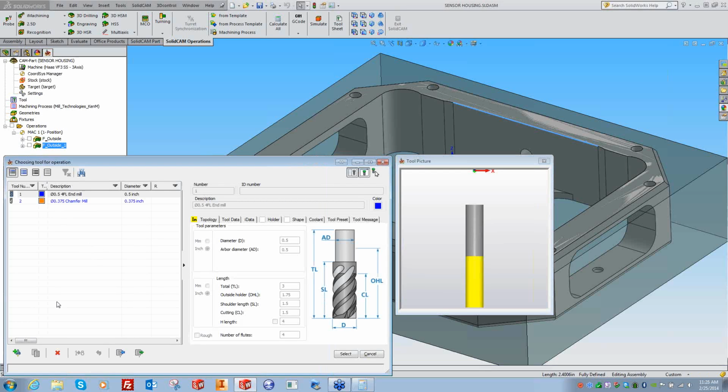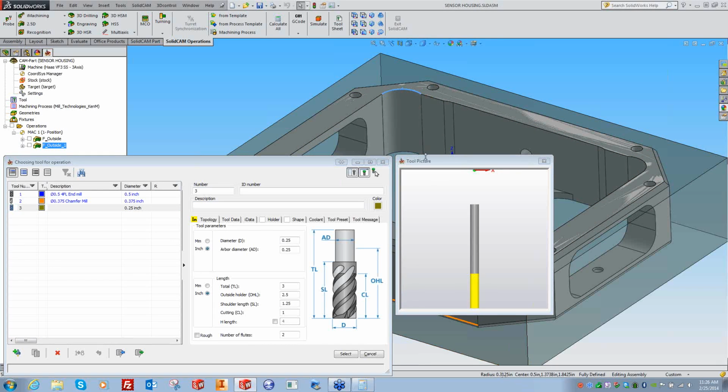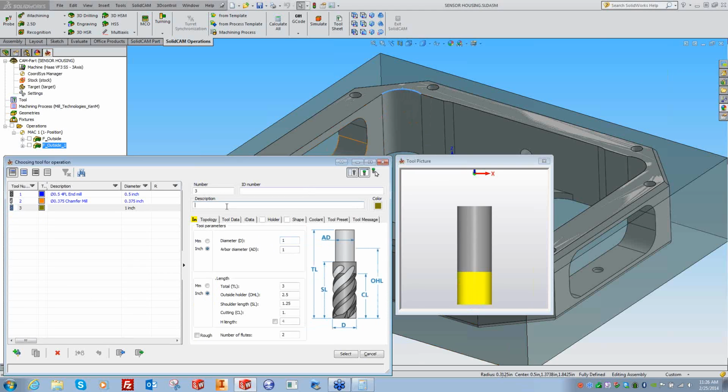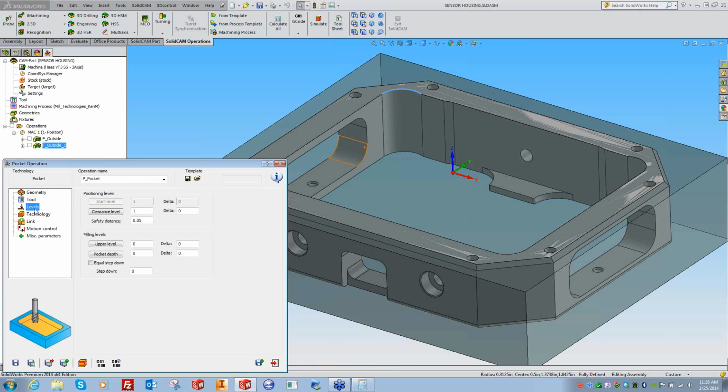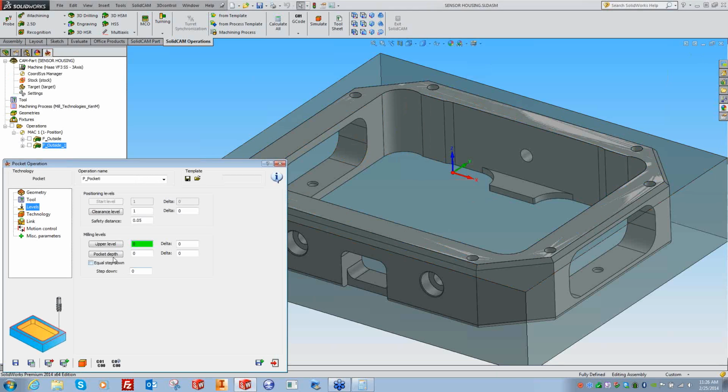And we'll use a much bigger tool. We'll use a 1-inch tool, because these corners here are actually created by a 5/8 tool, so we want to use a nice big tool here. And mill. All right. Let's do 125, 125, 125. That's fine. So I'm just trying to get the material out of here to start with, and then we'll do a rest